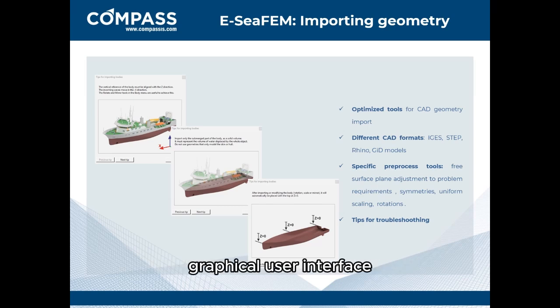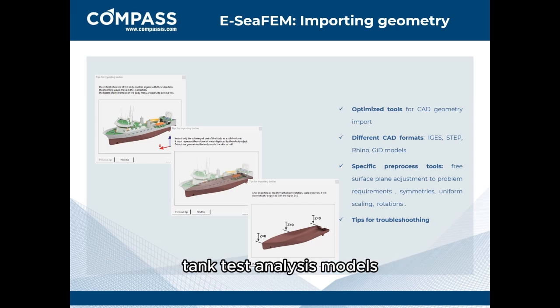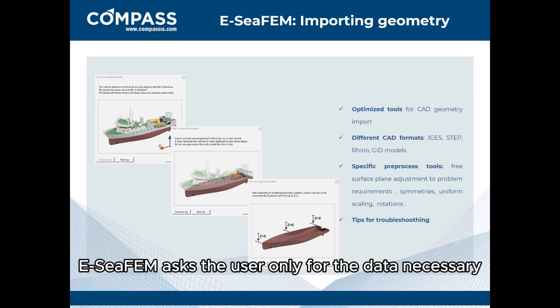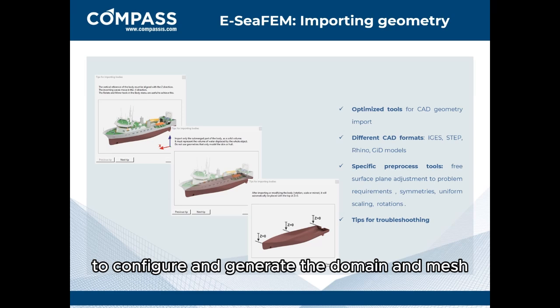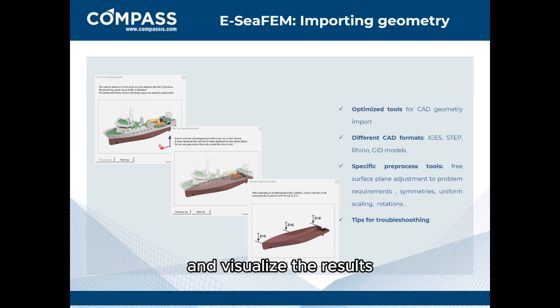E-SeaFEM is the new advanced graphical user interface that enables quick and easy creation of towing tank test analysis models for time domain seakeeping FEM simulations using the powerful Tdyn WindTunnel solver. E-SeaFEM asks the user only for the data necessary to configure and generate the domain and mesh for the simulation of behavior at sea in a few clicks, as well as to run the analysis and visualize the results.